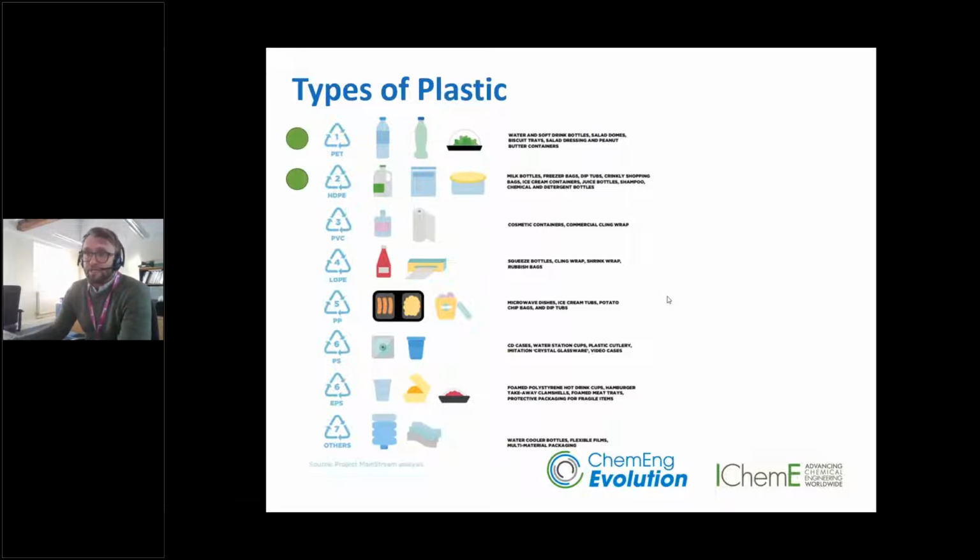As a bit of a general take, PET and HDPE, there are established commercial operations for recycling these materials, and they typically have a value. There are then materials like LDPE, so low density polyethylene, and polypropylene, where there's a developing market in areas, you will be able to recycle these materials, but not everywhere. And then there are a group of plastics where really there aren't commercially operating examples of these materials being recycled.